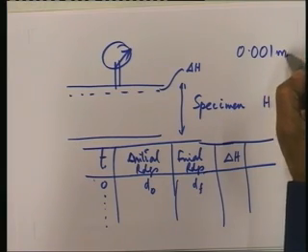The dial gauge starts showing a stable, somewhat stabilized value of reading, and it is therefore important that in situations where the dial gauge reading is very small, we must be able to measure it very accurately, which means that we need a dial gauge of very high accuracy. The least count of the dial gauge must be such as to capture even small changes in thickness of the clay specimen. Usually, we use a dial gauge with a least count of 0.001 inch or millimeter.